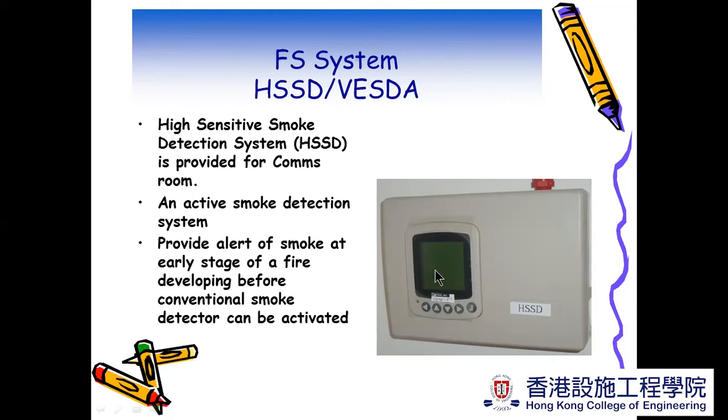So when there is a fire, the smoke or the dirt will be inside the room, and then the active sampling taken will compare with the basic standard data that this alarm panel has stored. If they found some differences, they will activate the alarm. So it could be quite sensitive sometimes, for very early smoke detection alarm system, right? Sometimes too early, maybe.